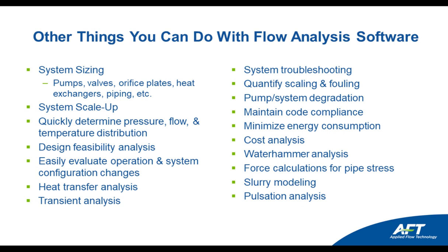When you're trying to figure out how to make changes to your piping system, it's really useful to have a flow model to help you predict how those changes are going to impact the behavior of your system. But if the system has been in operation for a long time, your flow model would initially be based upon clean piping. So you need to build in the corrosion into your flow model so that your model matches results.